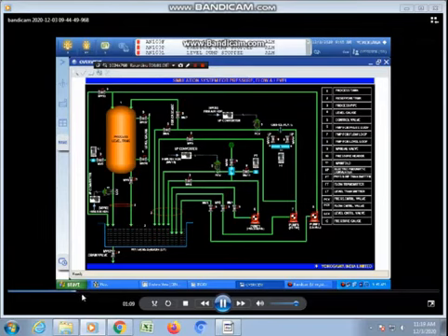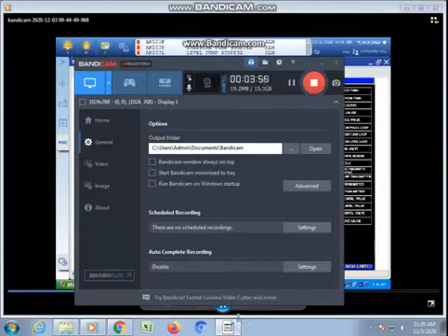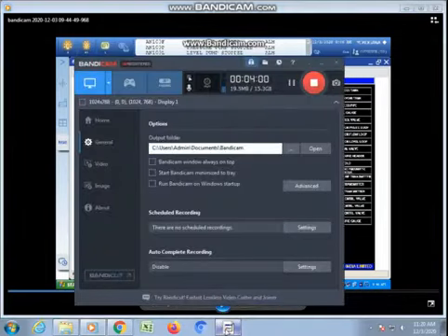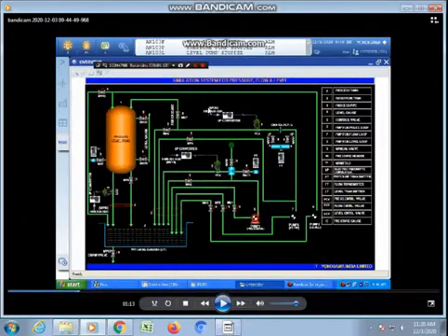When you take the operation and double click this pump, the pump on/off condition will come. Whenever we want to start any pump, we can double click the pump diagram in the overall control system, and the pump face plate will come. We might have seen what a face plate is.